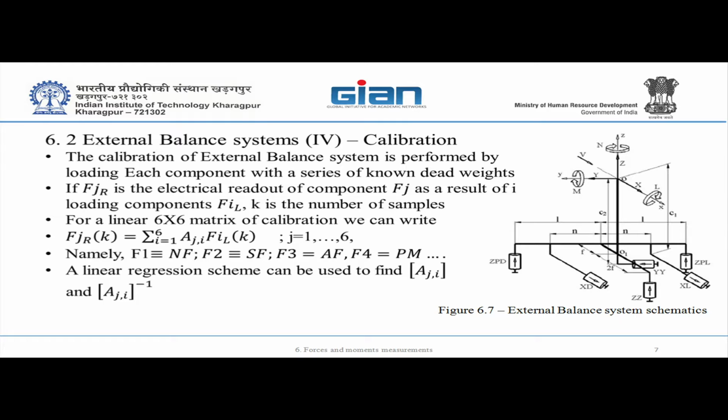One thing I didn't explore in the material, but it's good that you know generally, is to use dummy struts. There is a dummy turntable, symmetrical to the real one, and you have dummy struts which are not sensing and touching the aircraft. Then you make a sweep and measure the difference between with dummy struts and without dummy struts.